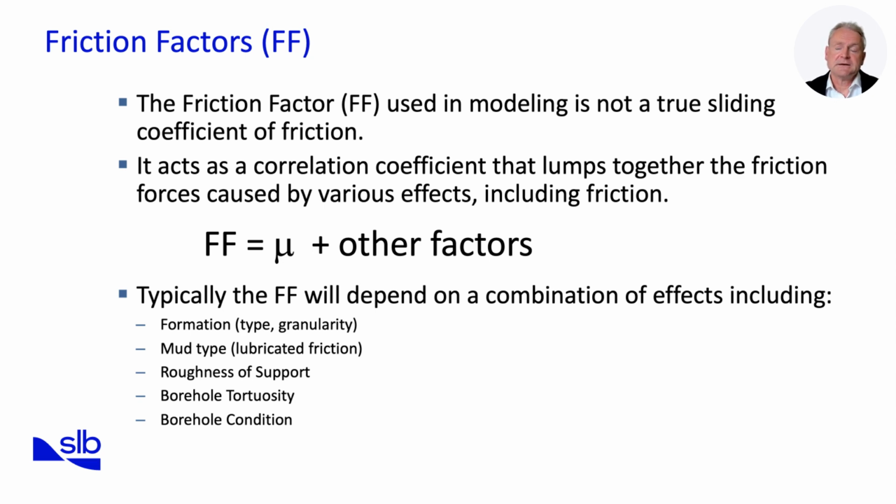By understanding these influences, drilling engineers can assign realistic friction factor values to torque and drag models. This enables more accurate predictions of pickup weights, slack-off loads, and surface torque, ensuring the drill string design remains within safe operating limits.